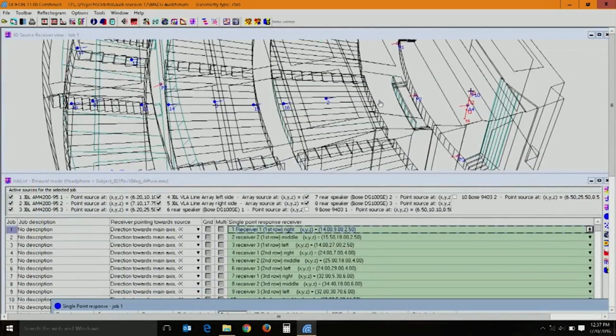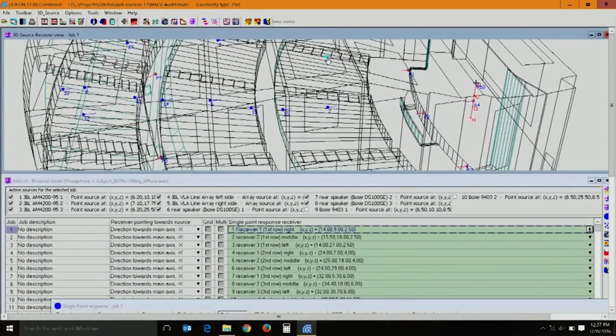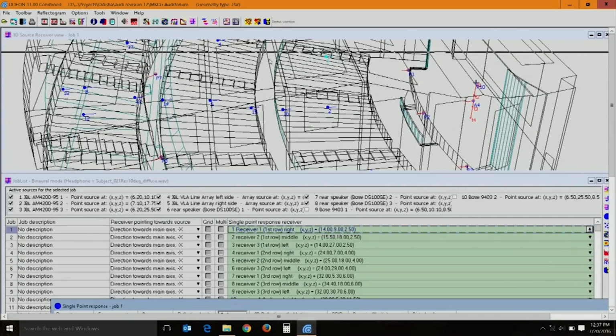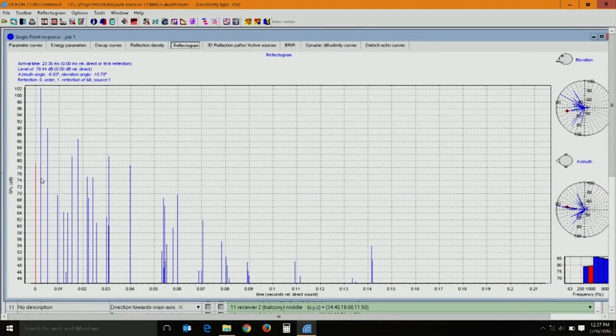The person is sitting close to the corner; this is the direct sound, then he gets the first reflection, this is the second reflection, third, fourth, and he starts getting reflections. If you are interested in musical performance, you will probably, as I said, stop at 80 milliseconds somewhere here. Whatever comes before is good, whatever comes later has to be avoided. Now the late reflections are relatively less.